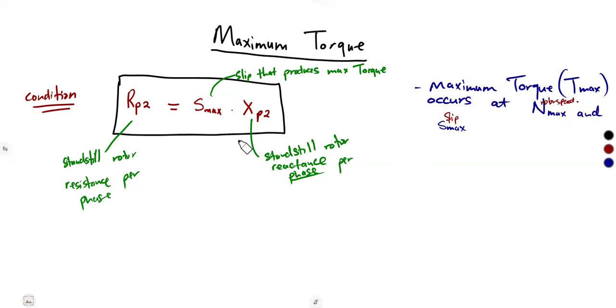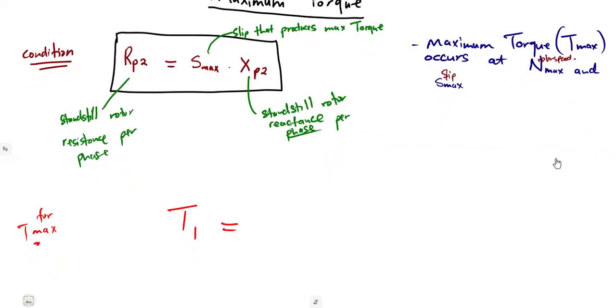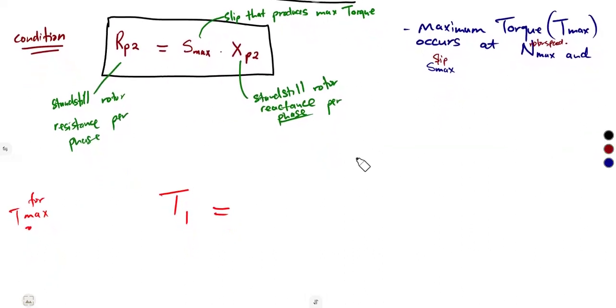So with these conditions, how do we calculate that? It follows that T1, the formula that is used for maximum torque, is taken from T1. So it follows that T1 is the torque at any slip except for when it is maximum. The torque that you're talking about can be determined at any slip that you're given, but not at maximum slip, because at maximum slip, we are talking about maximum torque. So please do not get confused on that one.